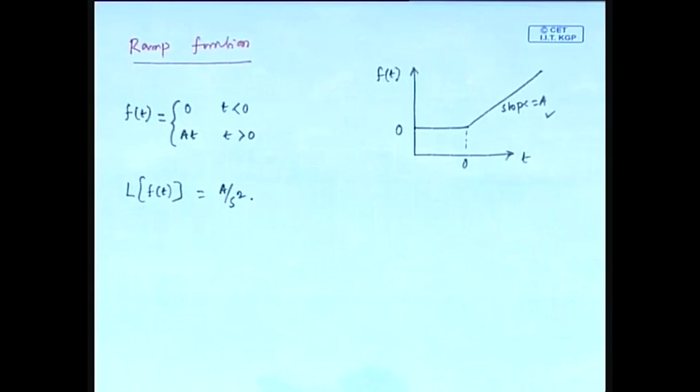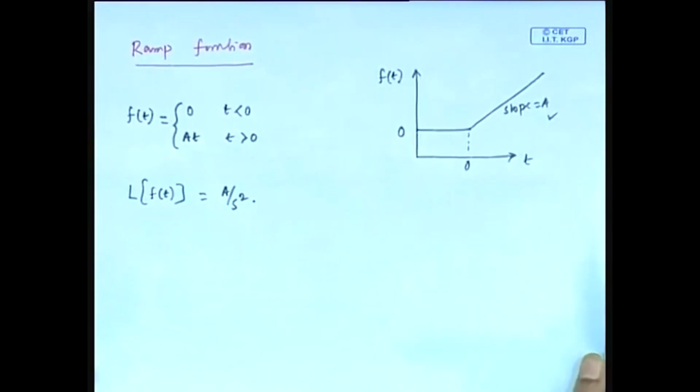So, what will be the example? Gradually open the steam valve, so that Q increases linearly. Fine. Gradually increase the steam valve, so that Q changes linearly, and the ramp ends when the valve is fully open. So, these are the forcing functions which are used to observe the transient behavior, definitely in presence of a control scheme, but presently we are not discussing the control part, we are just discussing the simulation results, I mean the model output.